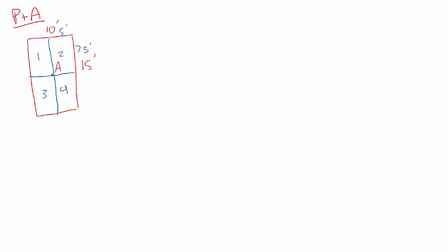So that being said, let's go ahead and first write down or recall what Z is. Z is 10 feet. B for each one now is the smaller of the 2 values, so B must be 5 feet, and L must be 7.5 feet because it is the longer of the 2. And now that we have Z, B, and L identified, we can go ahead and determine what M is.